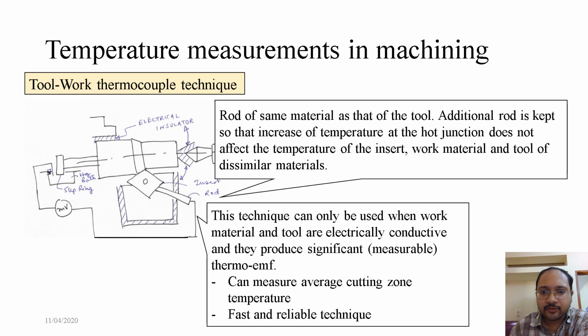The technique can only be used when work and tool materials are electrically conductive and they produce significant or measurable thermo EMF, which we have just mentioned. It can measure average cutting zone temperature, and it is a fast and reliable technique.